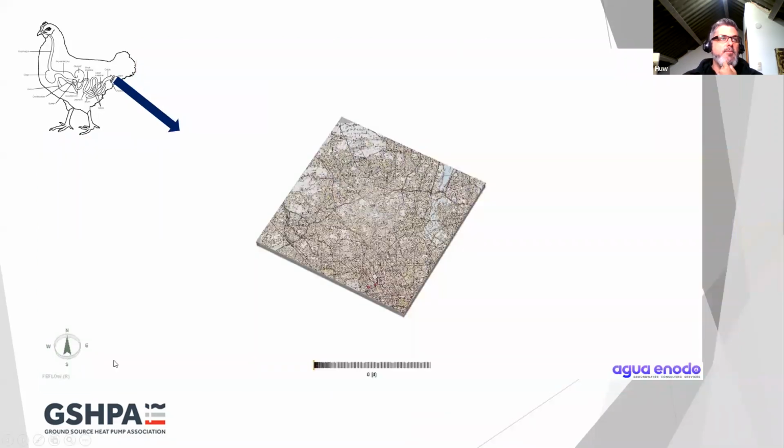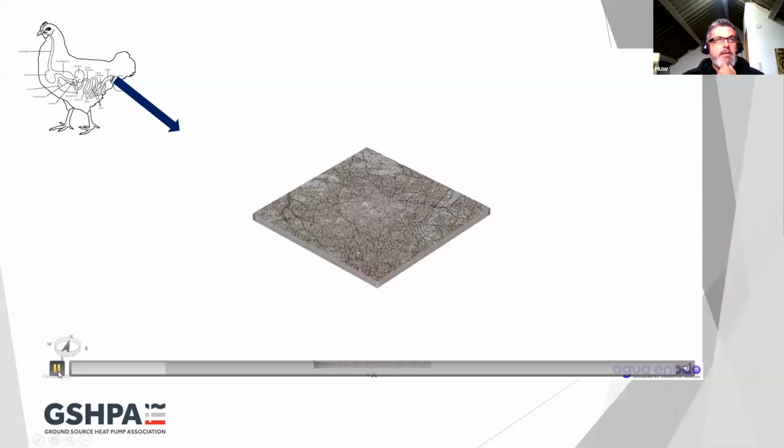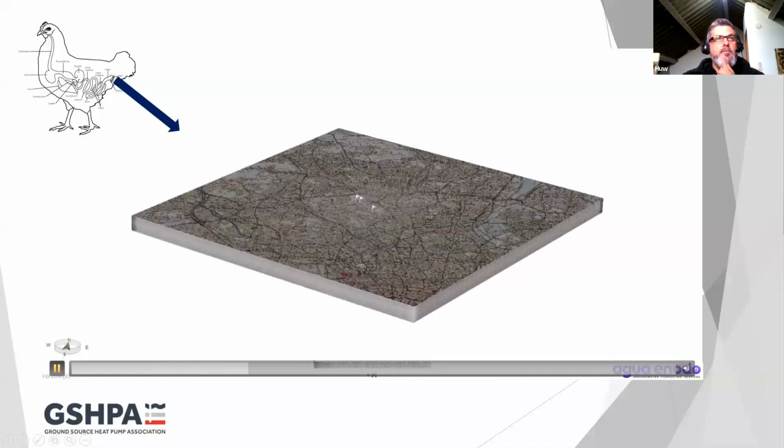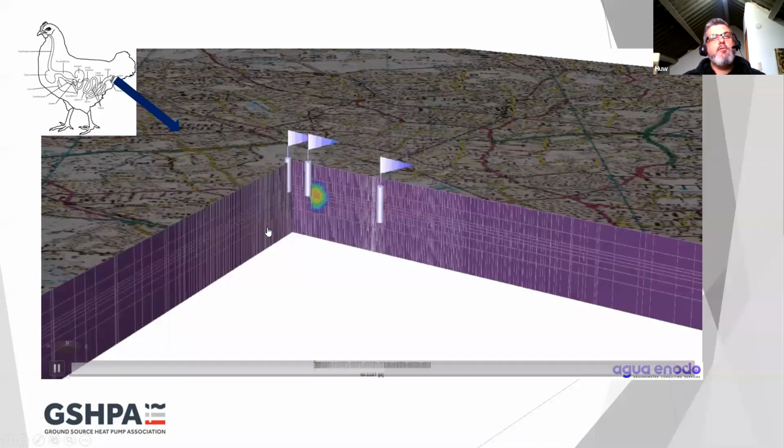This is the same theoretical site in London, just the model again. Nope, that's the same one. Let's try this one. That looks different. Same system. You can see that the groundwater model is replicating the flow through the aquifer, this time in cross section. And it's interesting to perhaps note that this is the top of the aquifer, this is the bottom of the aquifer. We've got most of the thermal transport going along within the bounds of the aquifer, very little vertical propagation of the thermal plume. It certainly predominantly moves with groundwater flow and moves within the bounds of the aquifer.